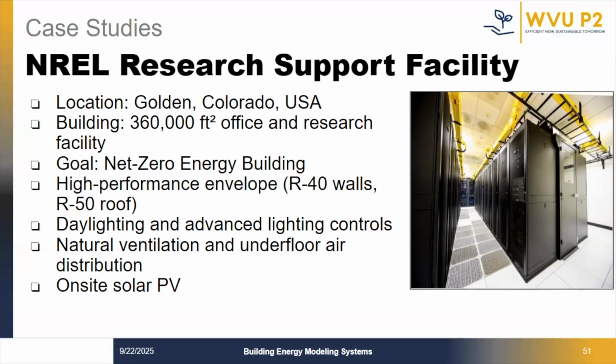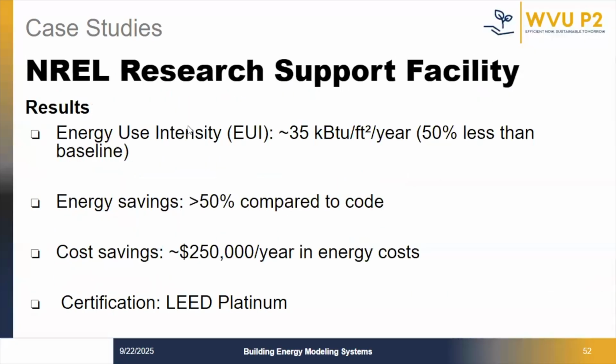They used energy modeling from the very beginning to design every aspect, such as super insulated walls at R40, natural ventilation, roof insulation with R50, solar power, daylighting and lighting controls. NREL research support facilities showcase how even energy intensive buildings can achieve remarkable efficiency.